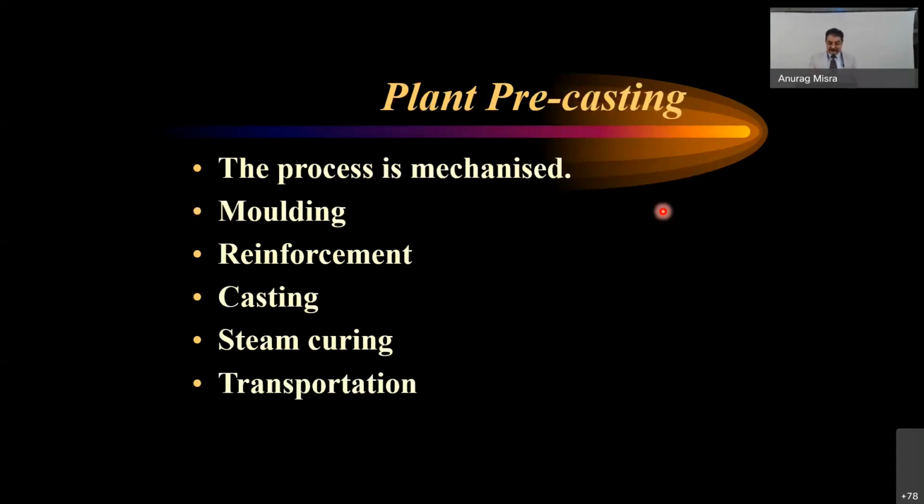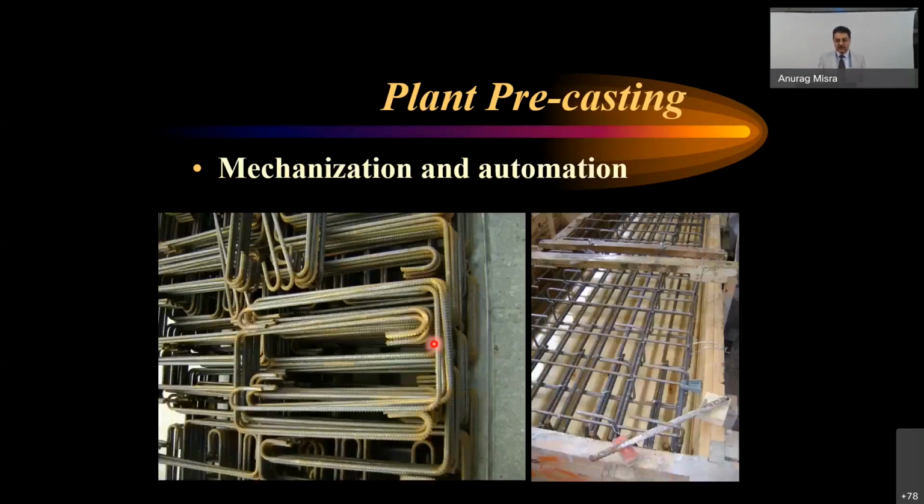So the plant precasting, I'm talking about now wet cast. The process I already said: the molds, you can do pallets or different molds. Reinforcing is normally done separately. Casting is done, then the steam curing and transport. Normally steam curing is deployed.